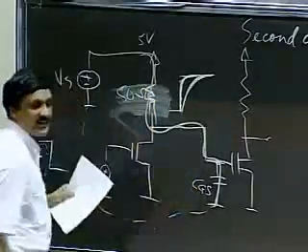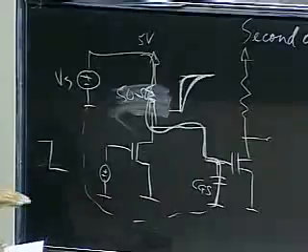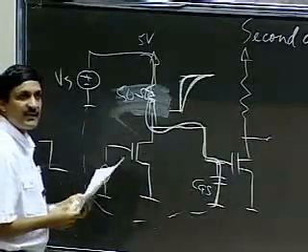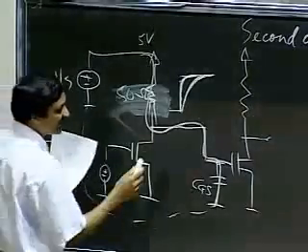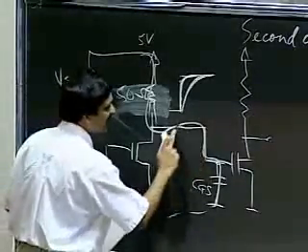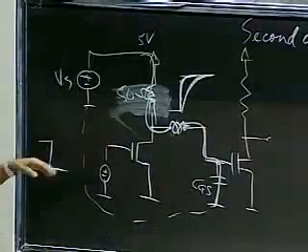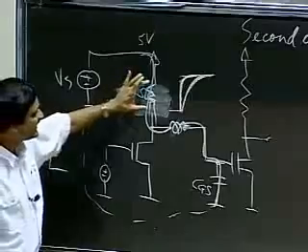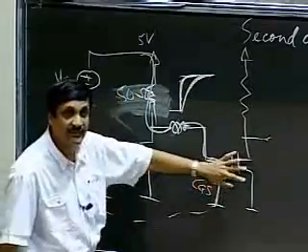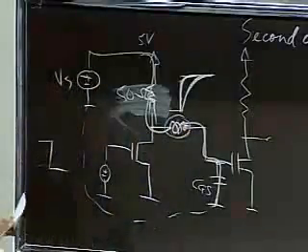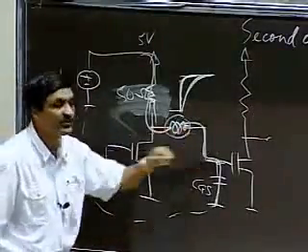And in fact, any current flowing through a wire above a ground plane, for that matter, can be characterized by an inductance. Okay, so I can model that by sticking a little inductor here. So my real circuit is not exactly a resistor and a capacitor, but my real circuit has an inductor as well that comes into play because of this wire.